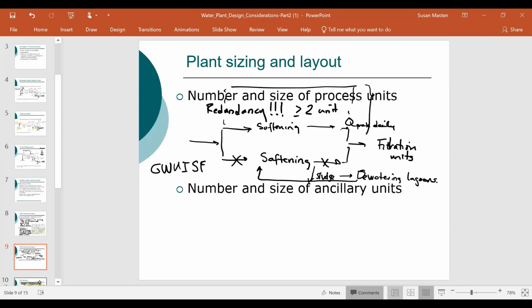That means that all the surface water rules actually are applicable to that groundwater system. They have changed the system so that they no longer recycle water back into the plant. And by doing that, they are now just a groundwater system. So only the groundwater rules apply. So yes, it's still legal to distribute water without treatment if it's a groundwater system, not if it's a surface water system.